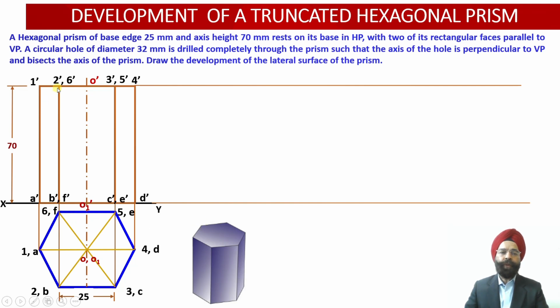So the front view projections corresponding to the vertical edge 6'F' should have been drawn as dotted projection lines in the elevation projection view. But we observe that this vertical edge 6F has been overlapped by the vertical edge 2B in the front view projections over here. So this vertical edge 6F has been overlapped by this vertical edge, which happens to be 2B, in the front view projections.